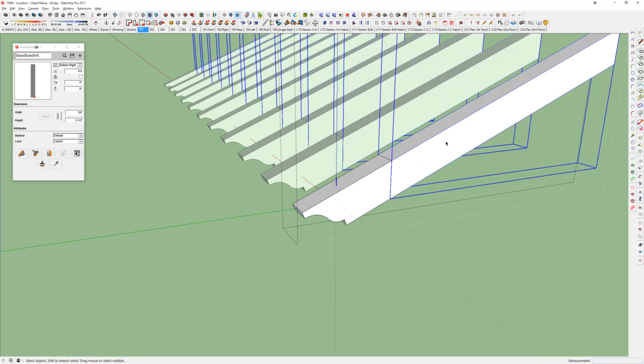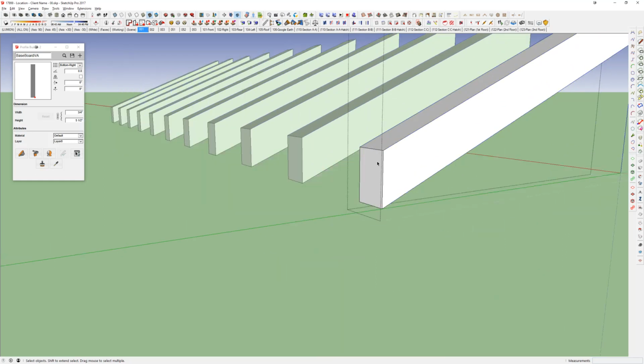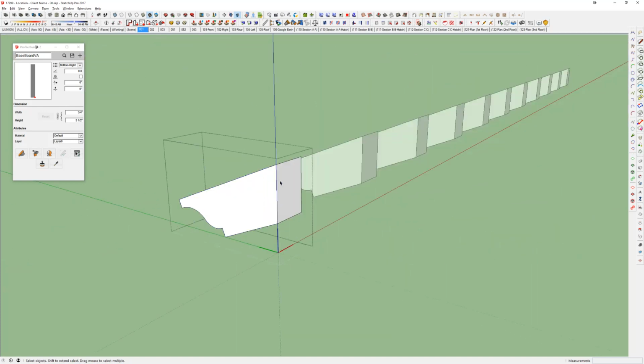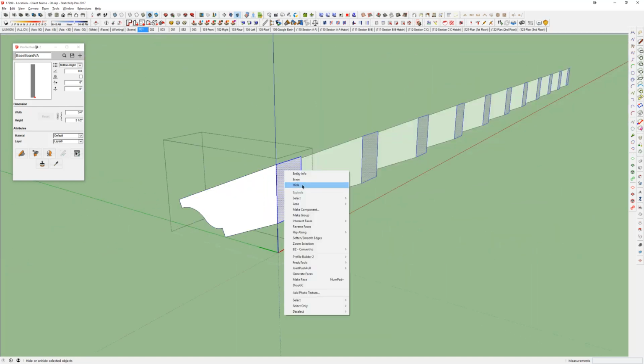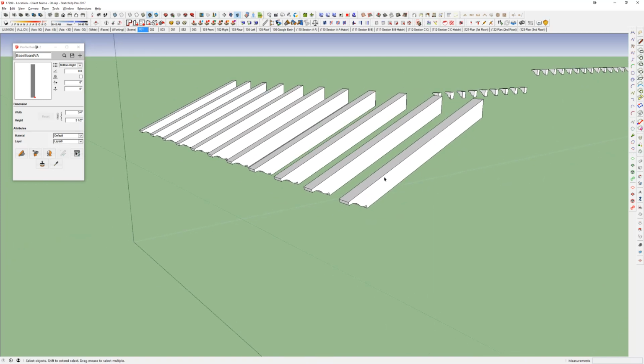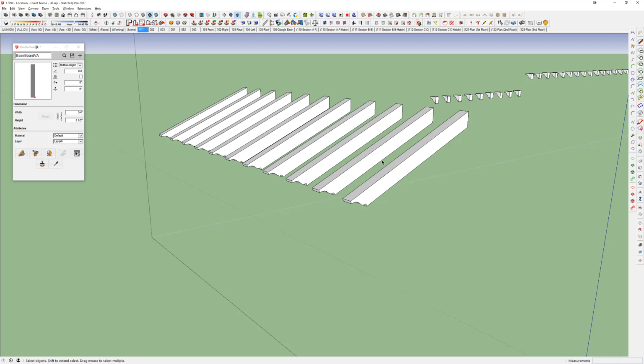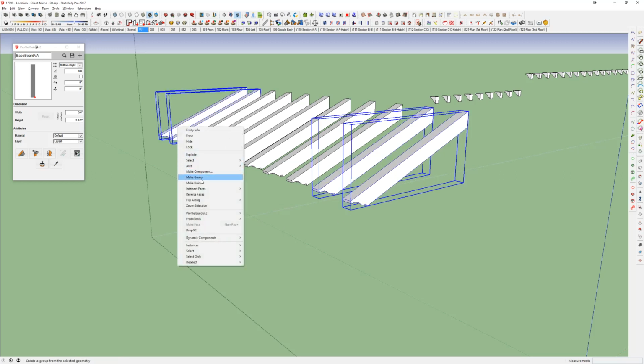And then simply turn this into a group. Now I want to get rid of this line, so I'm just going to come in here and hide that face and line, come in here and hide this face and line. So now they all look identical, and they currently are. If I hit my hidden lines, you see that I have my hidden lines here, but you can't see them while I'm modeling. Now what's great is if I make these four unique like I did last time,